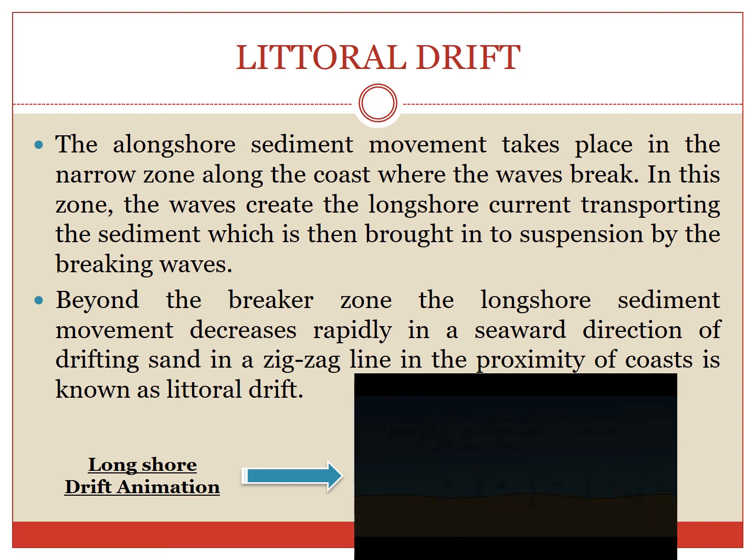So the longshore sediment movement takes place in the narrow zone along the coast where the wave breaks. In this zone, the wave creates the longshore current transporting the sediment, which is then brought into suspension by the breaking waves. Beyond the breaker zone, the longshore sediment movement decreases rapidly in a seaward direction. The drifting of sand in a zigzag line in the proximity of the coast is known as littoral drift.